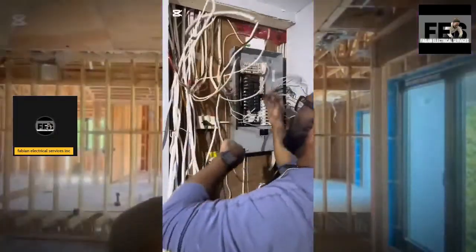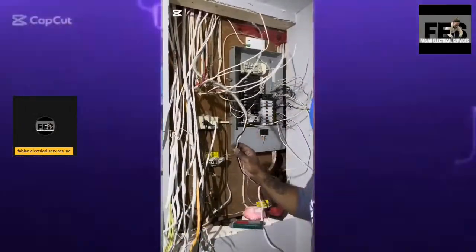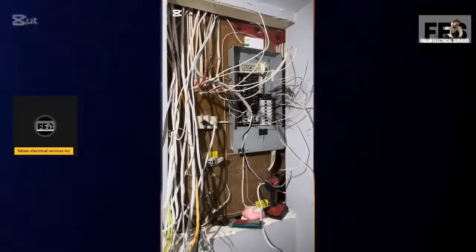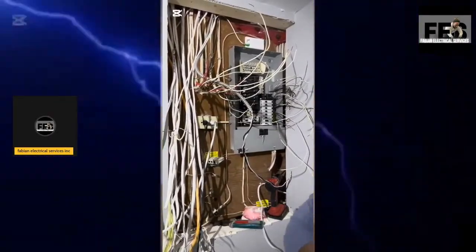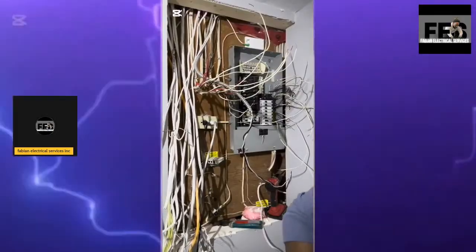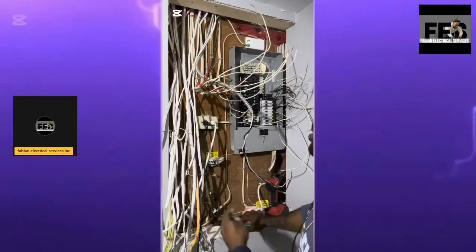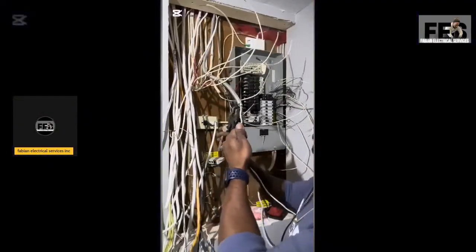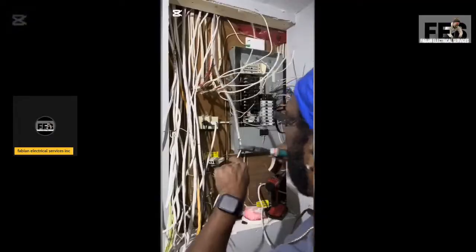What else do you have? You have your actual water tank, for instance. Your water tank might say on there a couple of amps. That's where we get our actual load for the actual circuit. And then what we do is we tally all those up and see what number we come out with.